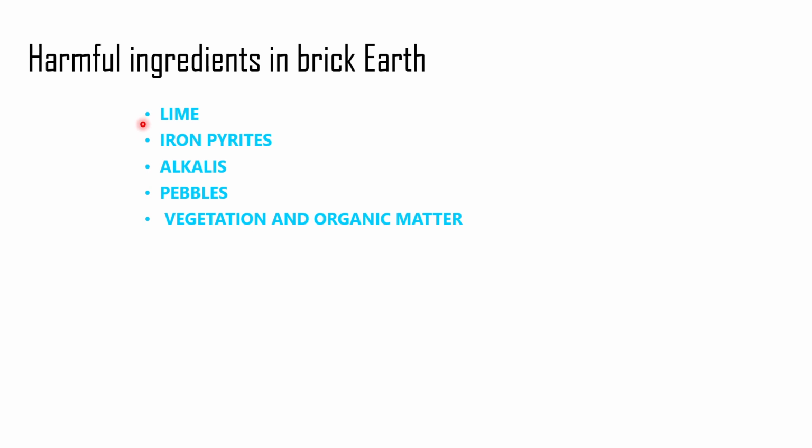Okay, because it causes unsoundness. Unsoundness means a small impact will cause a breakdown. So the quantity of lime should be minimum, less than 5% is desirable. Iron pyrites,